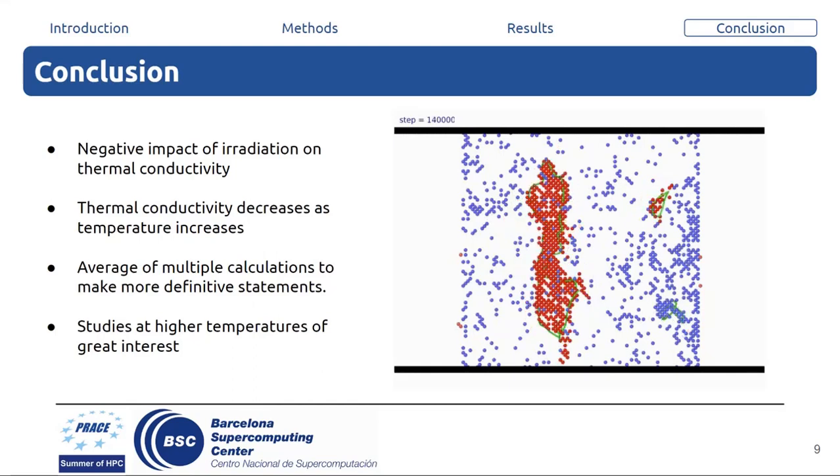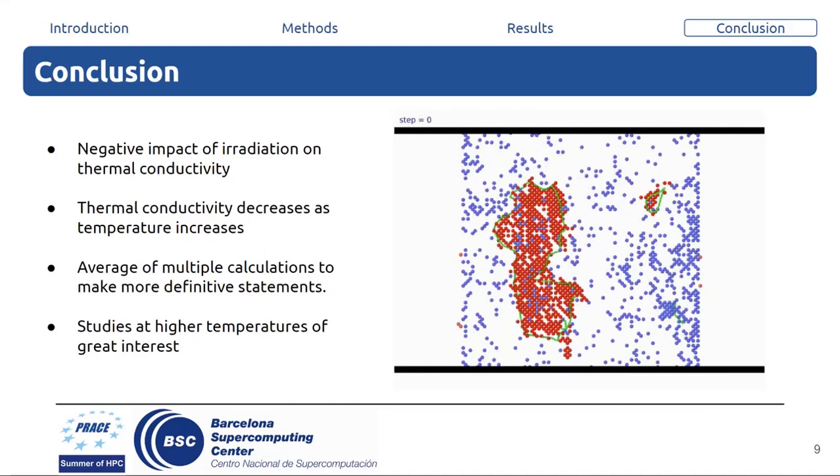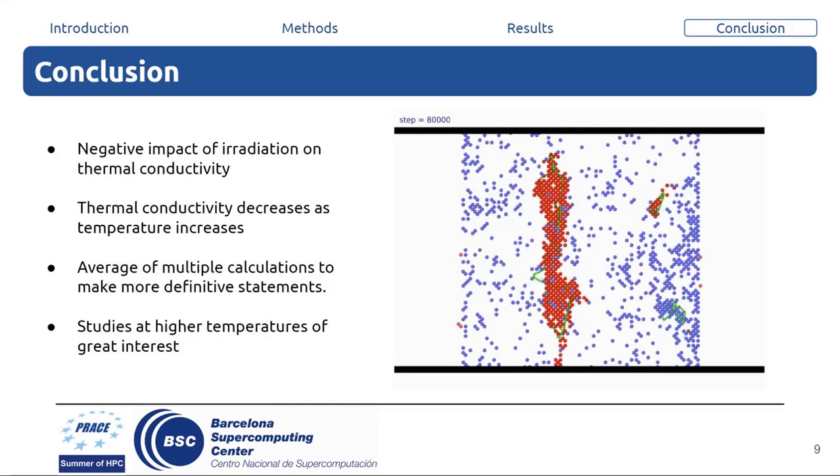The animation on the right shows an example for the evolution of defects as observed in the simulations. Red are interstitial atoms, forming extended defect clusters, and blue are vacancies. The green lines indicate dislocation loops, a special type of defect structure.